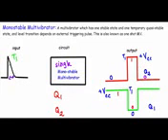Once the pulse comes from maximum to 0, the output will again switch back from 1 to 0. Now this is also known as one-shot multivibrator because here we will apply a single triggering pulse to control the operation of this monostable multivibrator circuit.